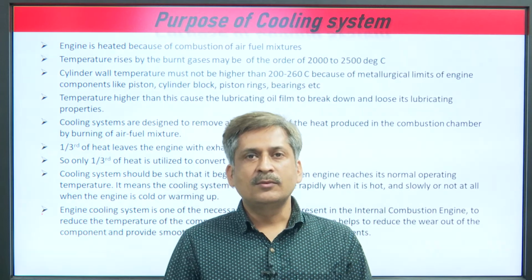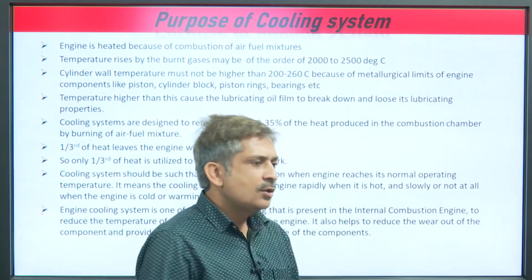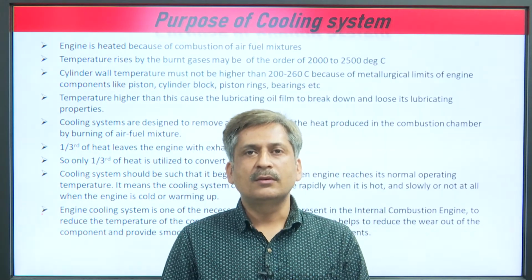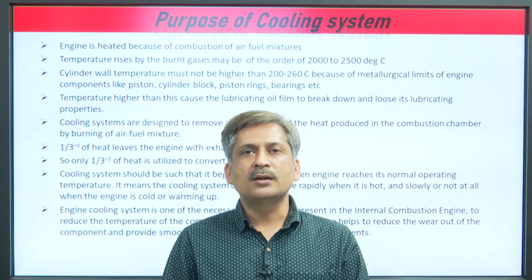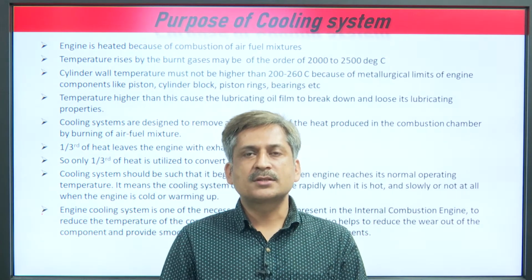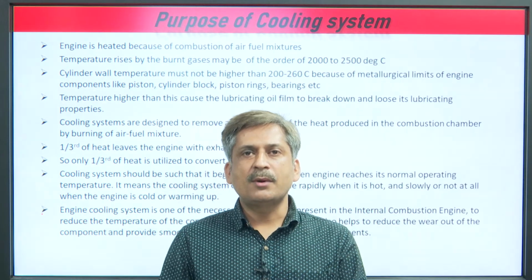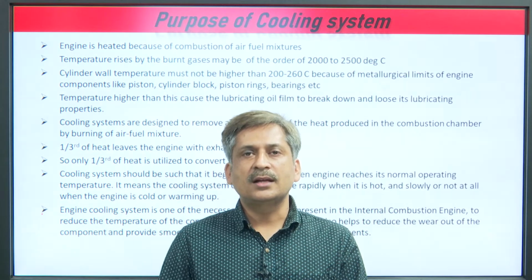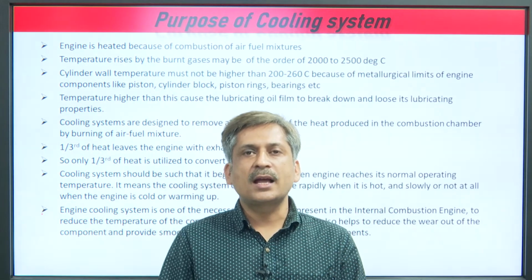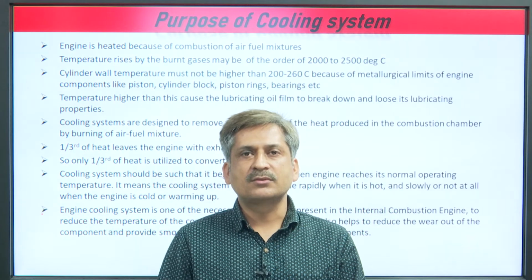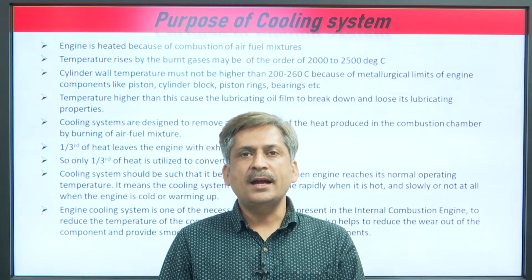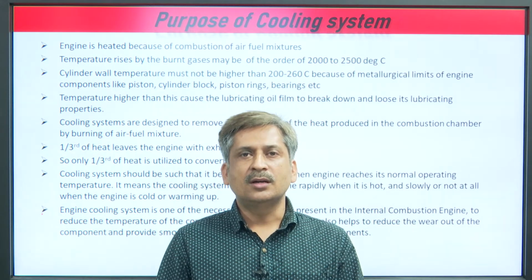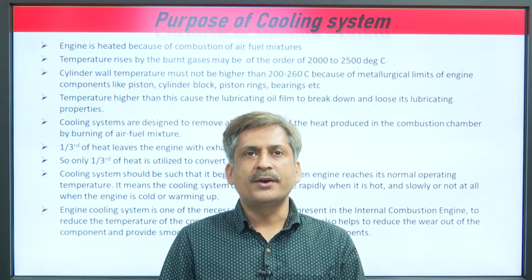As per the first law of thermodynamics, this amount of fuel energy is only partially converted into useful work, because some amount of the fuel energy, which is heat energy, is exhausted through the exhaust with the combustion products or exhaust gases, and some amount is lost in the cooling of the engine. So, why is cooling required?